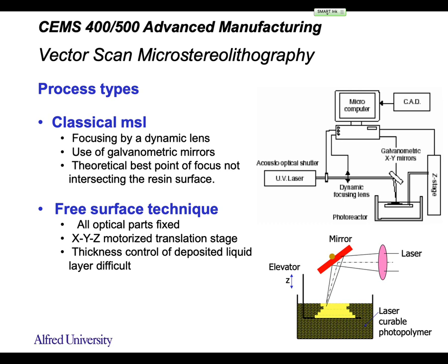And there's another challenge for this focusing, right? For this focusing method, if you imagine you have this focusing lens here, what happens to this laser spot? It may have a good focus at this position, right? But what about here? No, right? It won't be a focal point. The ideal focal point will be at this plane, right? So if you are printing at a large scale, this will give you a lot of error, right?